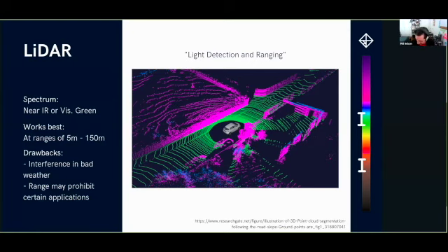But what I can tell you is that a single LiDAR does have points of failure. For instance, because of this focused beam of light, the shorter wavelength, you can actually read finer, smaller objects. But what this means is that the finer, smaller objects might be water particles in the air. It could be fog, it could be rain. And so if you're working outside, you could actually be getting the signature of rain in your LiDAR, which you don't want. It's not going to be helpful, right? So this interference of bad weather is something that autonomous cars, for instance, have to contend with, as well as anything outside working with a LiDAR.